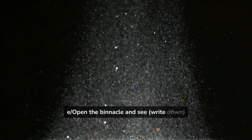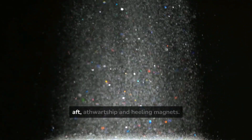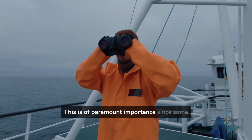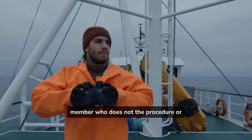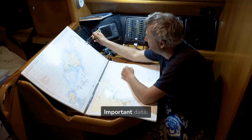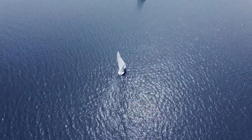E/ Open the binnacle and see, and write down, where the permanent magnets are: fore and aft, athwartship and heeling magnets. This is of paramount importance since sometimes the magnets have been changed by an unprofessional or maybe by a crew member who does not know the procedure, or they have fallen because they were not protected. Important data. F/ Check the local variation.